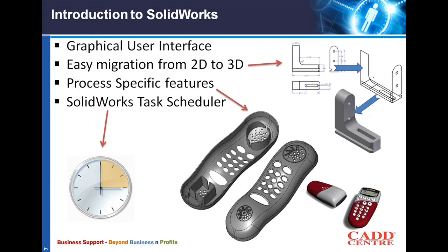So what you do here is open a separate Task Scheduler application which comes with SolidWorks, and you show the path where the files have to be converted. They will be converted into the new version which you want. So you don't require manual input. You can give a schedule time, starting at 9 o'clock and ending at 5 p.m. And also you can do processes like printing the documents and creating drawings automatically by using templates, etc. You can do all this using SolidWorks Task Scheduler.